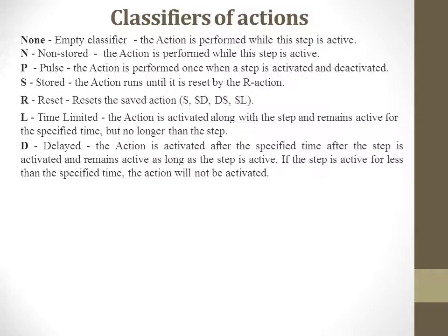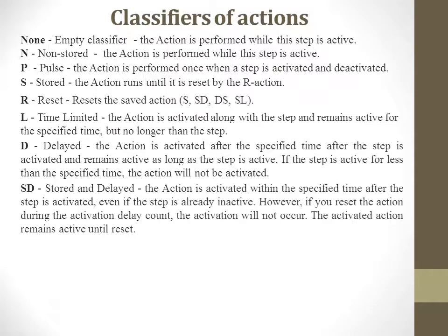The action is activated after a specified time after the step is activated and remains active as long as the step is active. If the step is active for less than the specified time, the action won't be activated.